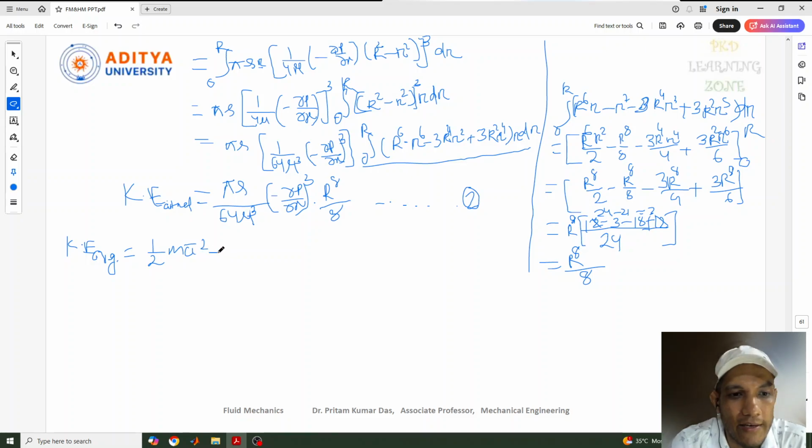For this also we need to consider this value per second. Similarly, the mass flow rate per second we can write here, again the same concept is going to be used. So this is rho A u bar, so with the average velocity, this is already the average velocity, that is squared. So if you write this kinetic energy value, in total it will be half rho A u bar cube. This kind of concept we have already discussed many times previously. So this is the final one.